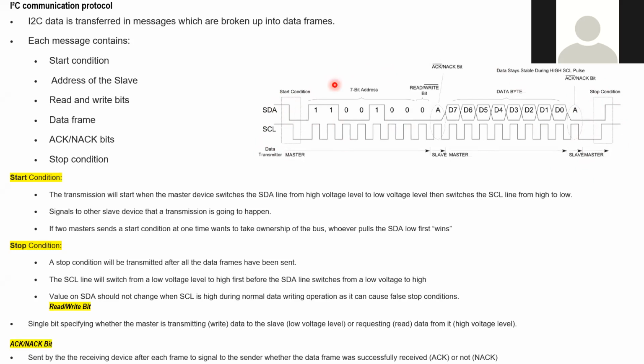I told you we have a 7-bit address, and an 11-bit address is also there. So you have seen this is my 7-bit address, 11000100. After identifying my 7-bit address, I can understand how many slave devices I have connected. Are you clear or not? We were saying nearly 128 devices can be connected, so maximum 128 devices are connected now. Depending upon some logic frames, they have kept an 11-bit address. Here we have used only the 7-bit address.